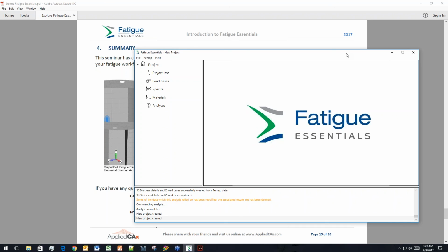Even on the aerospace side, a lot of it is stress life. If we had a huge user base looking for strain life analysis, that's something we can look at. Most of the basic functionality is there. It would just be updating the rainflow algorithms and some of that to accommodate strain life. But at this point, we just didn't see that as a big market, but maybe we're wrong.